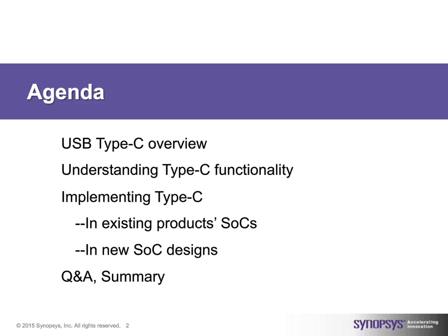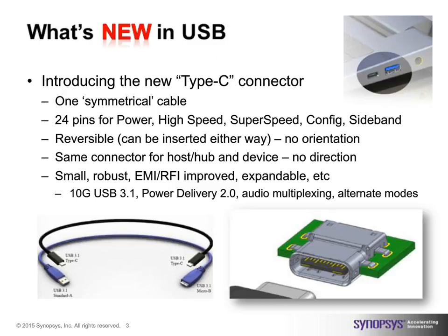So what's new in USB? Well, we're going to introduce the new Type-C connector. And with that, you just think by the name, is it just a connector? So Morten, isn't Type-C just another USB connector standard like the A connector, B connector, micro A, B connector, etc.? Or is it something more than that? Oh yeah, it's a lot more than that. It's not just a hardware change, it's a new symmetrical connector and cable. It's reversible. You can insert it either way. It doesn't have an orientation. It doesn't have a direction. You can use the same connector for hosts, hubs, and devices.